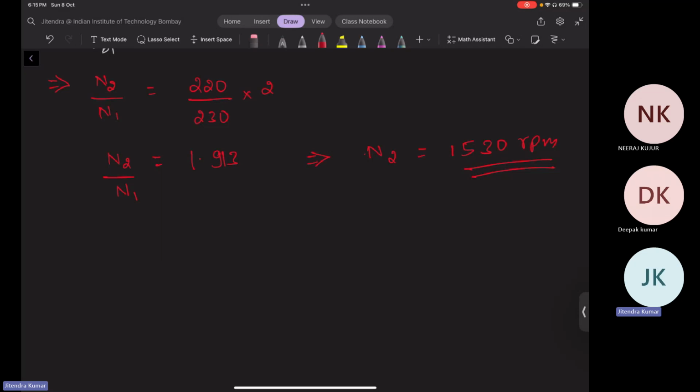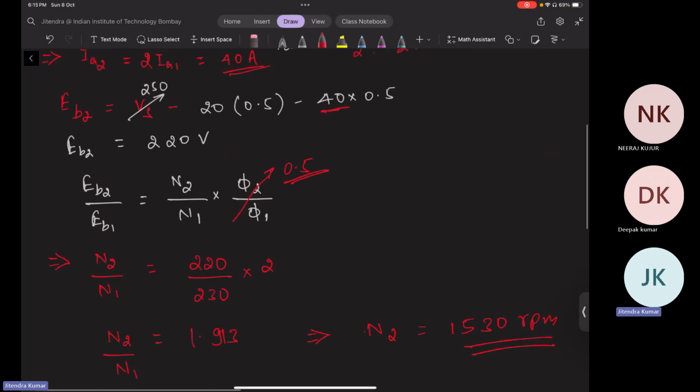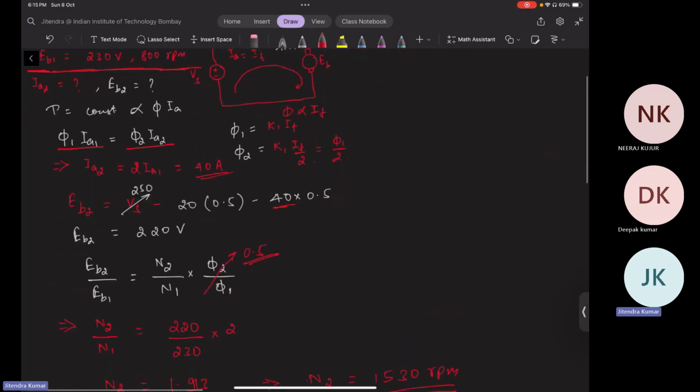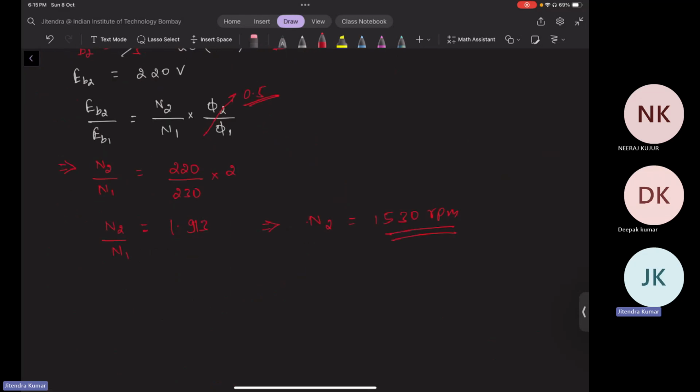That's another thing that in a DC machine it's a bit undesirable, like you cannot have separate control for two different entities. Whenever you try to change your output, you do not have control on the flux in the machine. So flux will come into the picture every time you change the armature current. That's why its characteristics are a bit different from all the other machines.